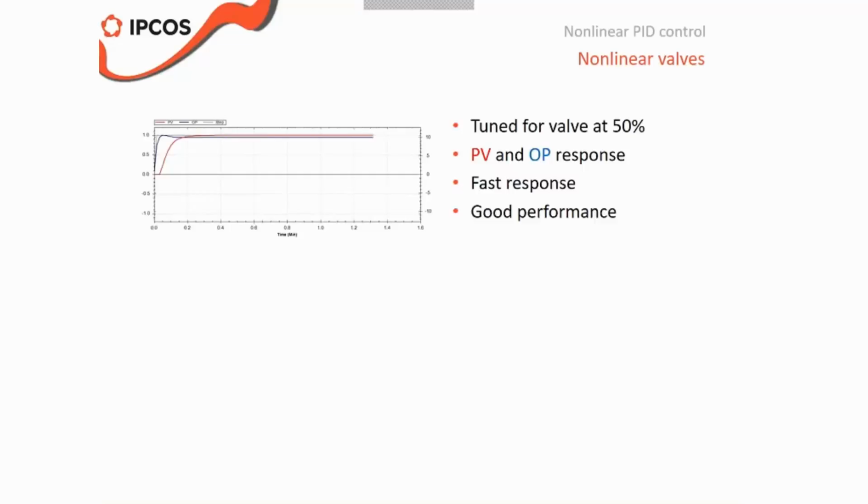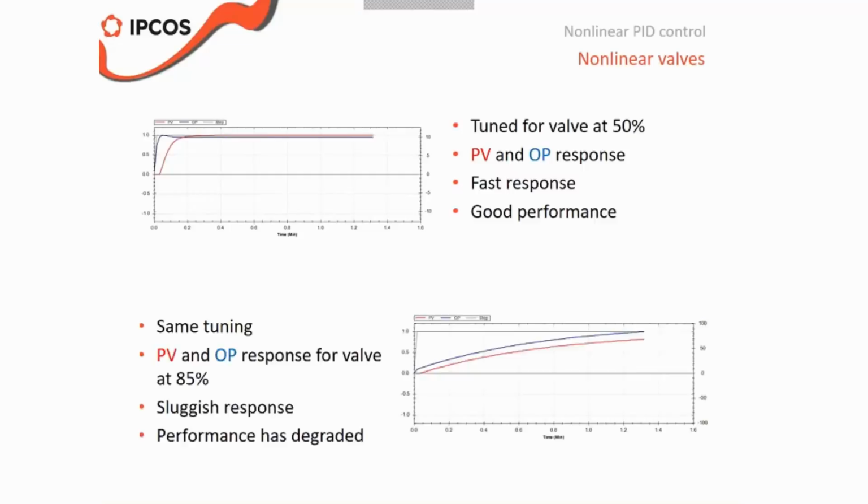Now let's assume that the plant was operated at 75% load. Let's see what happens if you go to 100% load, which typically would mean that the valve would open. If this would be a temperature controller cascaded to a cooling flow, controlling the temperature of a reactor, let's say an exothermic reaction, then obviously the cooling water valve needs to open to maintain the temperature if I increase the load to the unit.